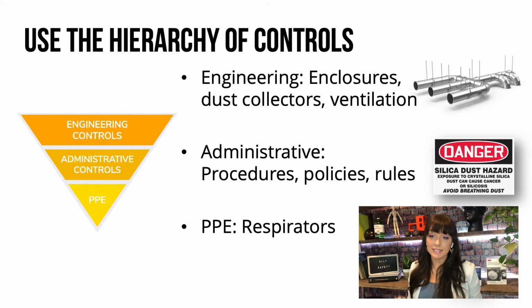And the last and least effective method are respirators, so your PPE. Respirators do definitely help, so I'm not downgrading that, but I am saying if you're going to approach it with a respirator, you want to use these other controls that are more effective first. The problem with respirators is people have to be fit tested, they have to wear them, they have to maintain them correctly, and they have to be clean shaven, because again, we're talking about those little tiny particles. If you are not clean shaven and you have a little bit of a gap around where that respirator is fitting, you're still going to be inhaling some.